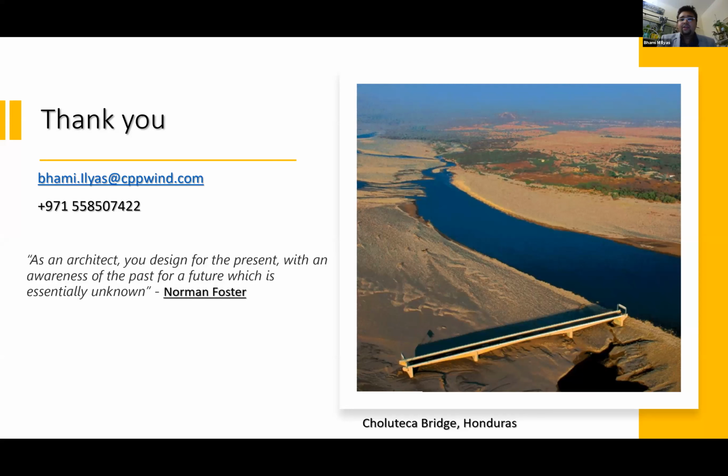Very interesting question, and it's a debatable one, and of current interest, in fact, because climate change, as you see around the world, is happening. But one of the key things we work on is looking at historical data. When designing a particular project, we look 50 to 100 years back, to see how the responses have been, particularly in hurricane and typhoon regions, how buildings were behaving, and we look for the peak loads. That's how we design. So yes, in a sense, we do take climate into account, but there is a lot of ongoing research on how we can take into account what may come in the future.